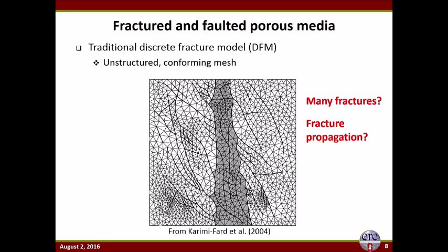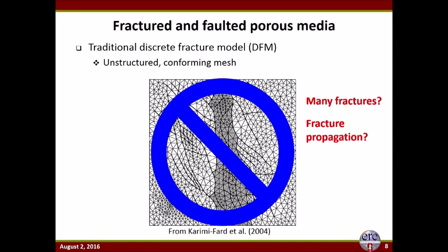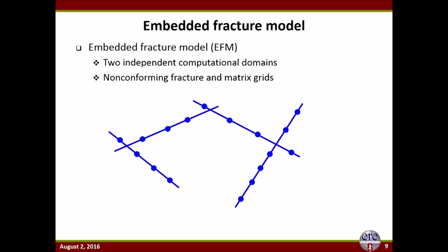And if you're interested in learning about things like fracture propagation, it's possible in this type of model, but it can become prohibitive from a computational standpoint. So really for those purposes, we tried to just avoid the use of traditional discrete fracture modeling, and we opted instead to use what we're calling an embedded fracture model. It's also just an extension of a finite volume approach, but the key idea in embedded fracture is that you treat the fractures and the matrix rock as two separate computational domains that are somehow coupled, and you'll see we couple it with just a source term that looks like a well.